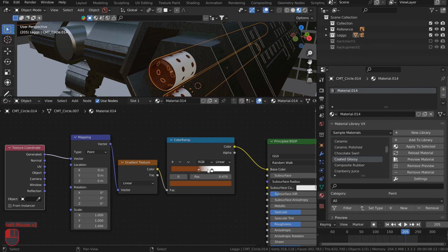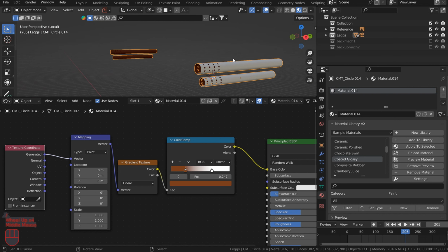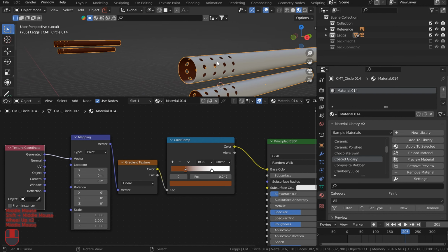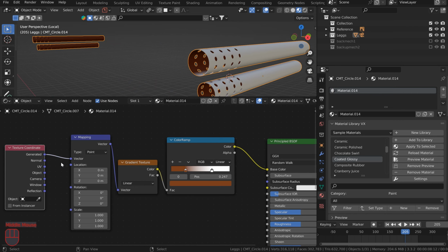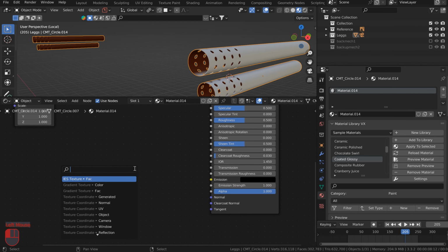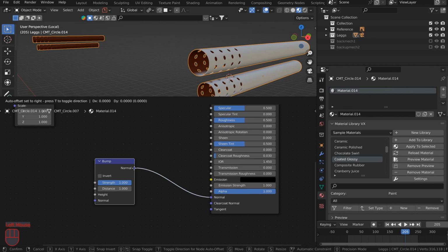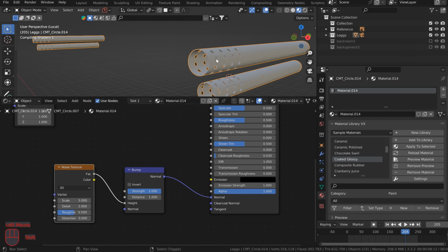And right now you can't see much because the gradient is not doing what we want. But let's slash and bring this up, get a really good view of what's going on, and hopefully I don't have to separate the selection and do anything. But this is a little trick that I use. It's very, very fun. Pull out the normals and let's bump map that. Just bump it. Pull out the height, type in noise, drop in your noise texture for height.